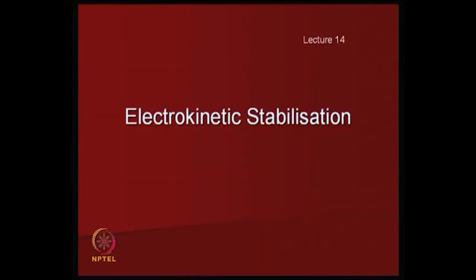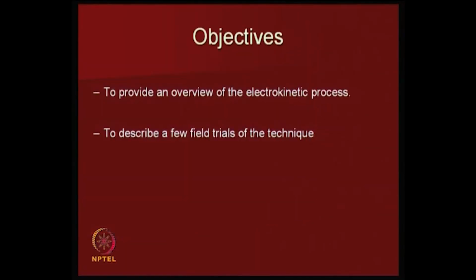The thing is, I just mentioned dewatering, particularly when it is in clays, how do you do that? This is very important, and we use this concept because we know that the clays are negatively charged particles, and we try to use this concept to dewater in the case of clays. So that is called electrokinetic stabilization, that we will discuss.